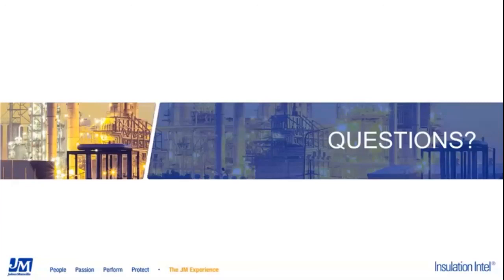Scott, this next one is for you, and that is, what is the definition of insertion loss? In the insertion loss, the way it is defined within the ISO standard is you're actually testing the noise level surrounding a pipe with a noise source on the inside of the pipe. You get the sound pressure level at the different octave frequencies with no insulation, no treatment on the pipe. Then you apply your acoustic insulation system and you measure it again with the same noise source. And then insertion loss is very simply just the mathematical difference between the sound pressure level reading or the decibel reading with no treatment and the reading with a treatment, and that tells you how many dB reduction in noise that you get.